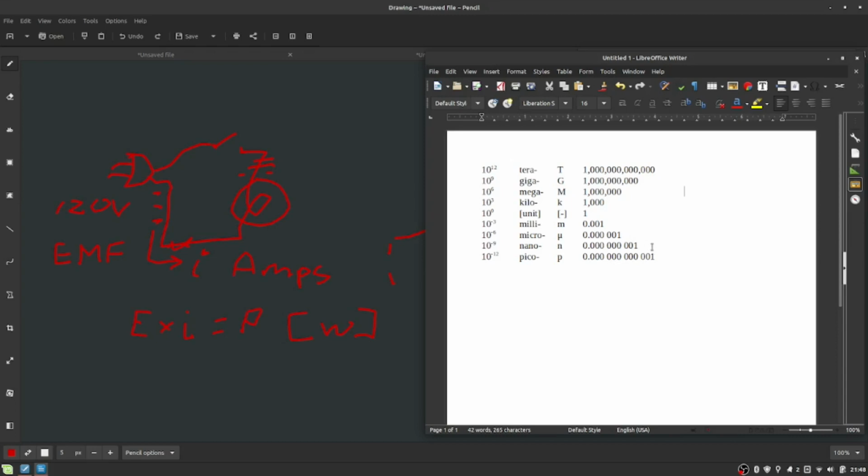But when you look at, let's say, voltage, you can have kilovolts, especially when you deal with power distribution systems, how to get power to entire neighborhoods or things like that. Very common. So I just talked about this capacitor here. Capacitance is measured in farads, which is a huge number. So more commonly, you will be dealing with microfarad capacitors, which usually uses this Greek mu symbol here, but sometimes it gets written just as uF. You may deal with nanofarads, which is 1/1,000,000,000th of a farad, and you very well might deal with picofarad capacitors.